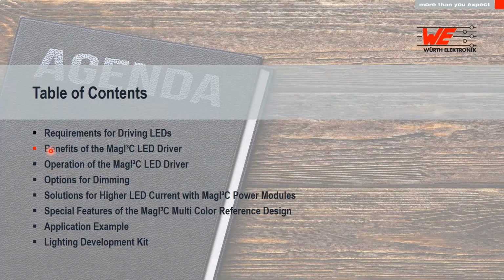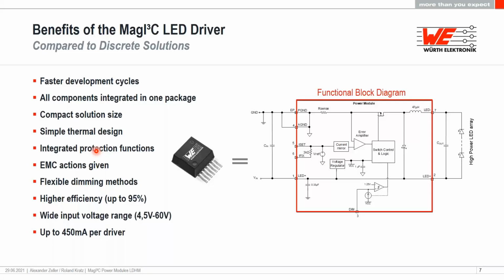Before we go into details, I will show you the benefits of the MagIC LED driver. Here you see the MagIC LED driver. This LED driver includes all components which are inside this red square. External is only the input capacitor and the LEDs, and the output capacitor is optional. You can put it in for better EMI, but it's not needed for operation.